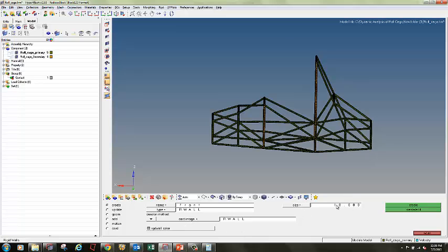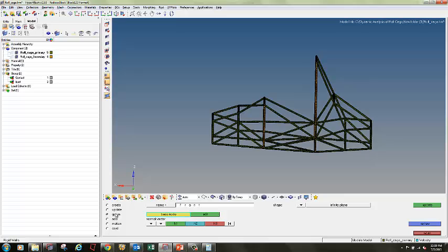This size doesn't mean the size of the rigid wall. If you put 1, we'll create an infinite plate, a rigid wall. It doesn't matter if you put 10, it is just the representation. If it's 10 it is smaller, if it's 100 it's bigger, but that doesn't mean it will not impact properly. So we are creating the complete infinite plate. I will click on create, then I will go to the next step, that is geometry.